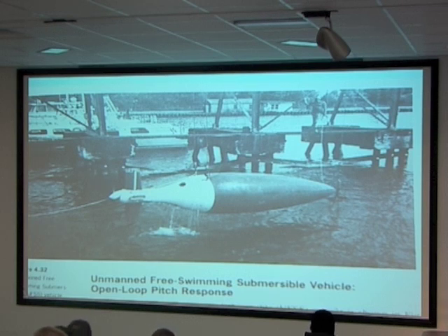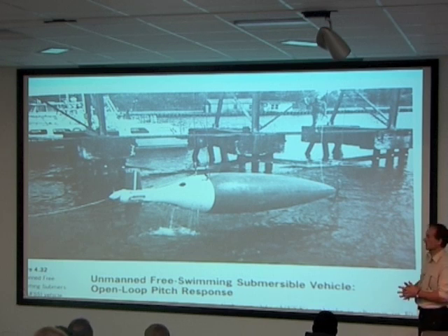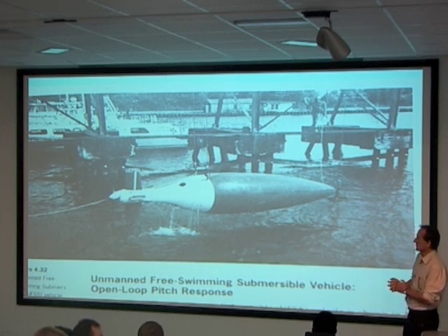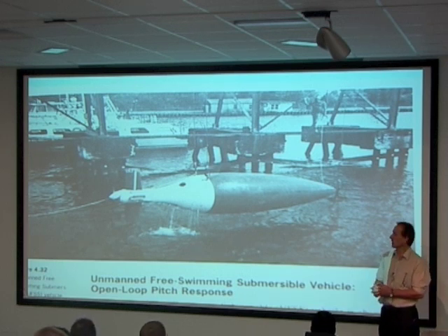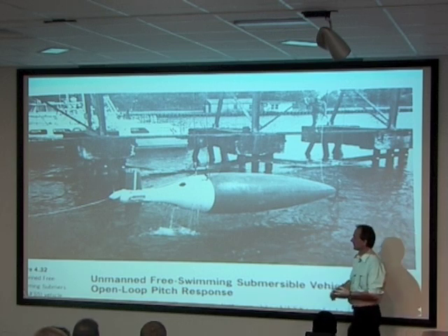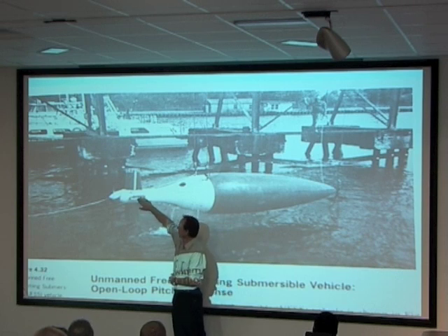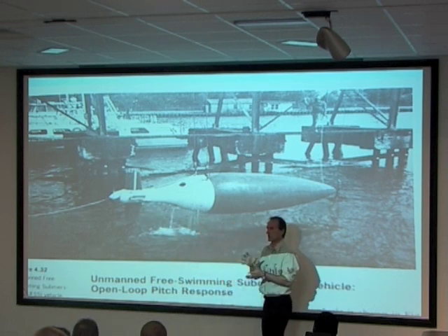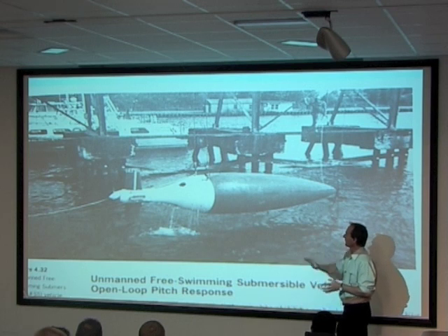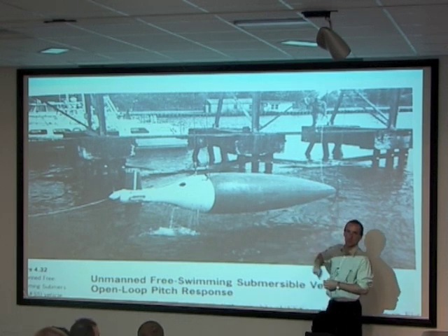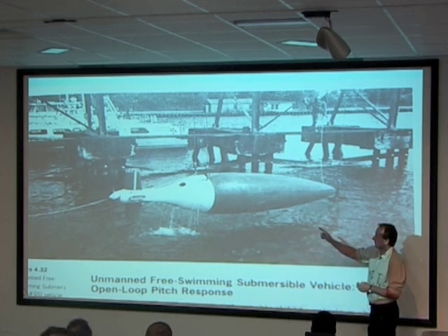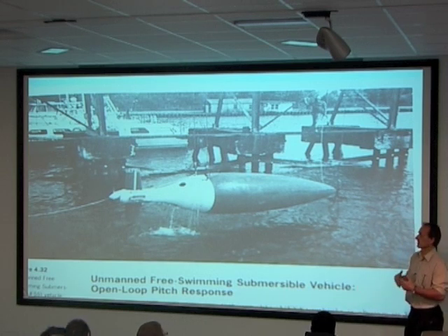What I'm going to be looking at, just to talk through the use of compensators, is the response to changes in pitch angle. So we've got these elevators, if that's the right word for them, I'm not sure, on the back of the tail there, and we're going to look at the relationship between the pitch angle of the vehicle and our input into those actuators.